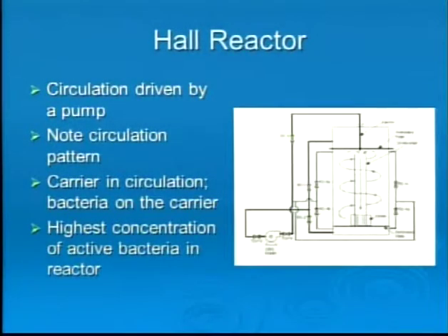Try it again. Essentially what we're doing in our reactor is circulating these little croutons, as Eugene talked about. These are a substrate, a surface media for the bacteria to grow and live on. We force the circulation of these little croutons in a circular pattern within the reactor, all stirred hydraulically.